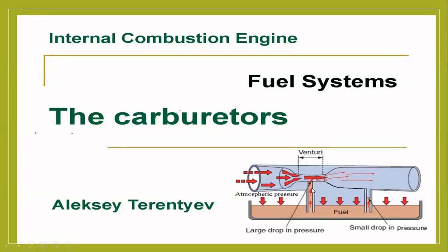According to this, pressure will drop. The fuel will be sucked because there is high pressure in the fuel tank. Here the pressure will drop, so it automatically sucks the fuel. So this is the mechanism of the Venturi. Wherever the word Venturi is used, you want to know this: it sucks the fuel by lowering the pressure and increases the velocity by lowering the pressure. The equipment is the Venturi.